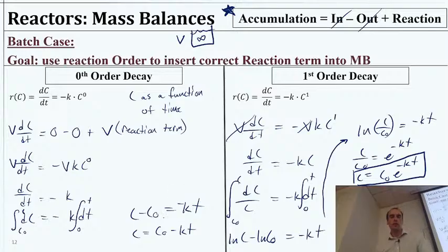Now what you'll note is you could solve this for time instead of concentration. Maybe you have the concentration, you just need to know how much time it takes. In fact, many times that'll be the case. We want to target a specific endpoint concentration. I don't want any more than this number of viruses in my water per liter because I know that'll be protective of health. Therefore, how much time does it take?